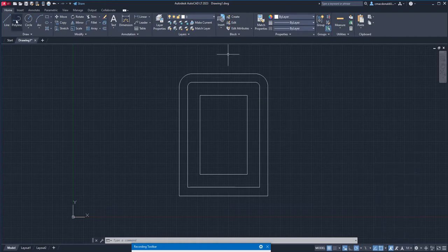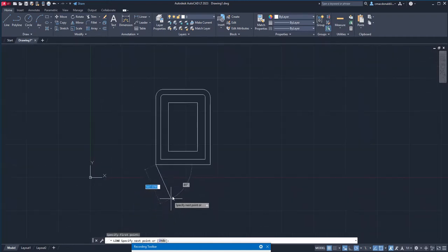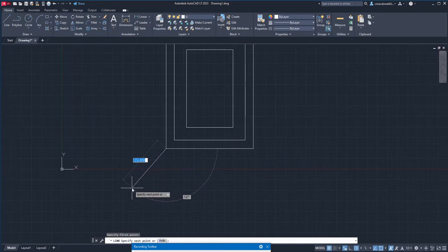We're going to try drawing a polyline. And because endpoint is on, it's automatically going to snap to this endpoint right here. See? As you can see, from the dynamic input command there, it says endpoint. So let's left click and bring our cursor anywhere out here. It doesn't really matter. We'll left click again.